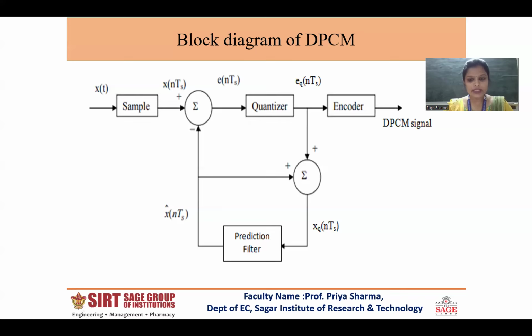Now coming to the decoder part, each received signal is converted back to an analog signal by a digital to analog converter after the serial to parallel converter, is stored, and then summed with the next sample received. This operation is similar to the accumulator used in the transmitter. The integration is performed on the analog signals, although it could also be performed digitally. So this is DPCM. I think you have understood the difference between DPCM and PCM.